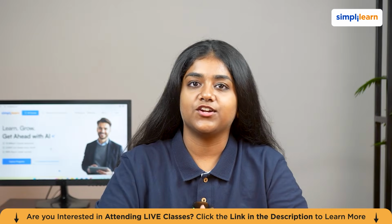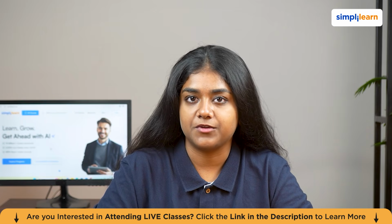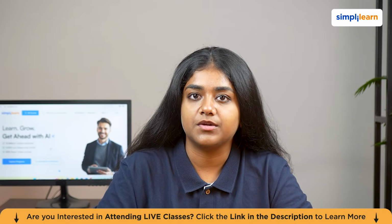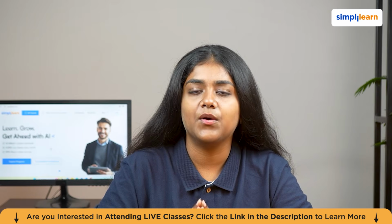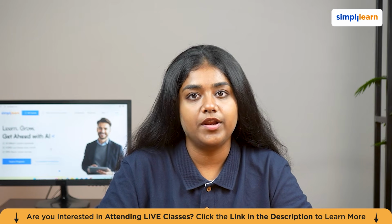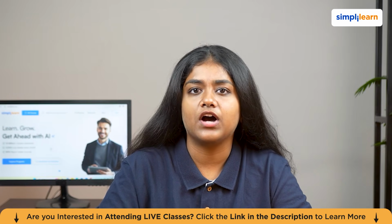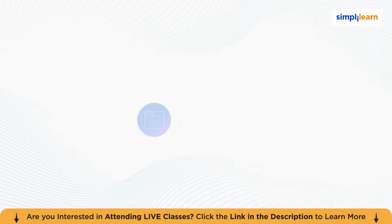So with that, we've come to the end of this module. In this module, we covered two core dimensions of measurement precision: repeatability, which captures equipment variation within a single operator, and reproducibility, which captures variation between different operators. We explored how a Gage R&R study is structured using multiple parts, multiple operators, and multiple trials to separate and quantify both sources of variation, giving a complete picture of how much of the total observed variation comes from the measurement system itself.